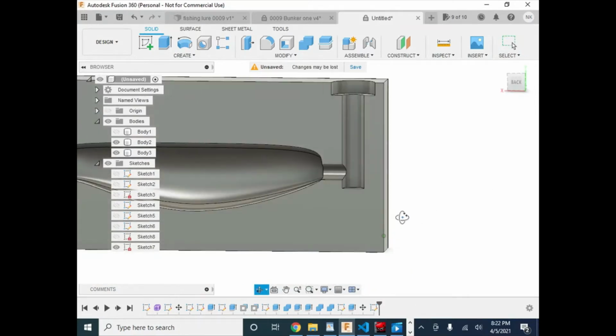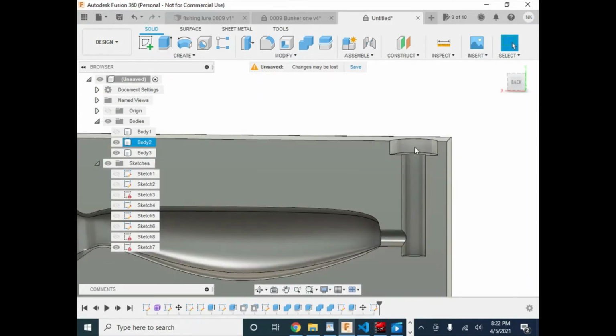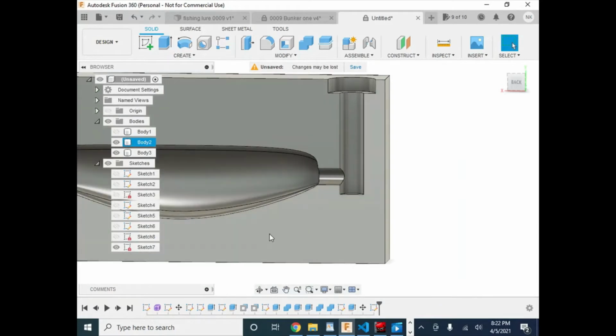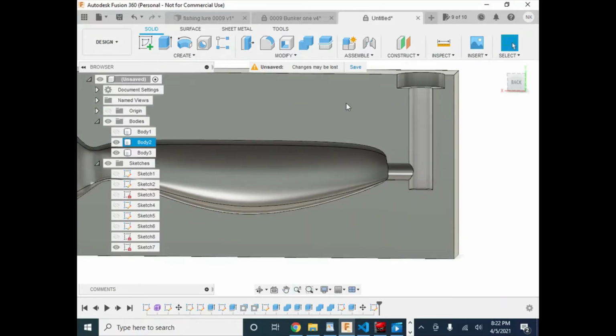If you've ever bought an injection mold for fishing lures, that would look familiar, right? Everything should look familiar. Sometimes you do need extra, because of the volume of your mold, sometimes you need to make this hole a lot larger, or you need some type of reservoir in here for this plastic to suck in any internal plastic. So just keep that in mind when you're doing this. You might have to play with that. Once you start learning how to do this, you might have to create a larger circle within there, just an FYI.